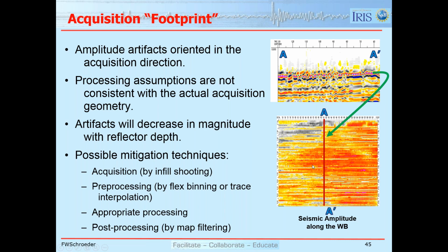And that's because this is a marine survey and the boat sailed west to east, turned around, sailed east to west, turned around, went west to east, et cetera, et cetera. And so it takes some time in terms of depth or two-way time to heal up the fact that we don't have continuous sampling along the surface. We have individual points, shot points, that are typically on the order of 12.5 meters apart.